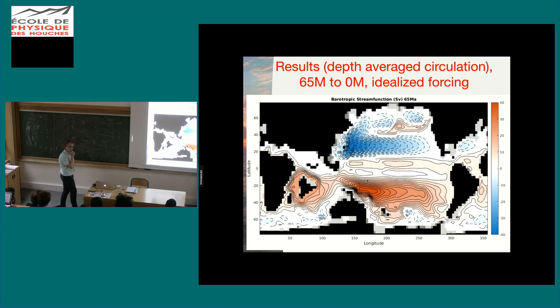By solving the eigenvalue problem. So you just solve this generalized eigenvalue problem, and you look at the eigenvalues, and when they're all in the left-hand complex plane, the solutions are stable. And for this case, they are.